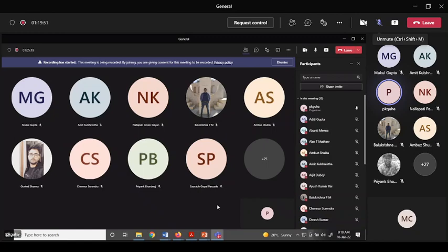Or if it is a 330 nanometer process, the minimum gate length, that is the channel length L, is 330 nanometer in that process. So if today's process node is 22 nanometer, that means the minimum gate length is 22 nanometer. The next generation process node might be 14 nanometer. That means the minimum gate length possible to fabricate by that fabrication lab using that process node is 14 nanometer.